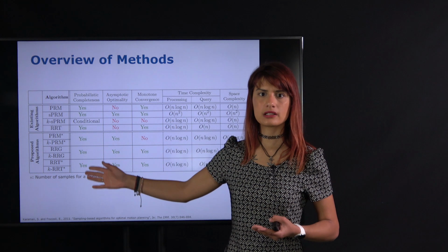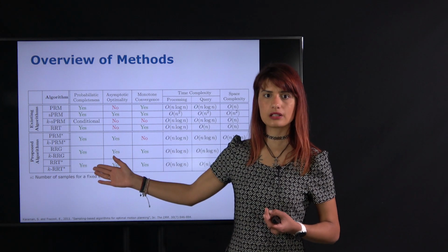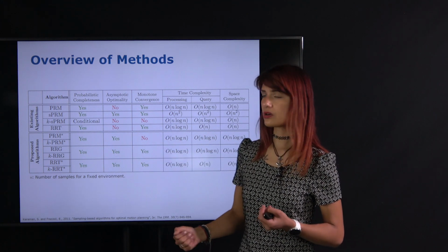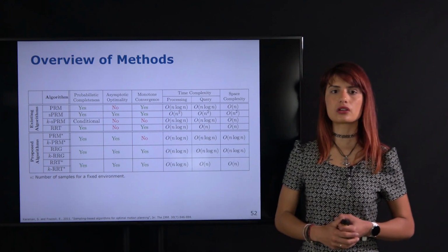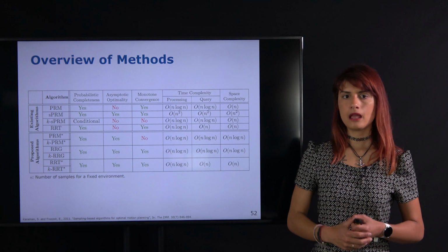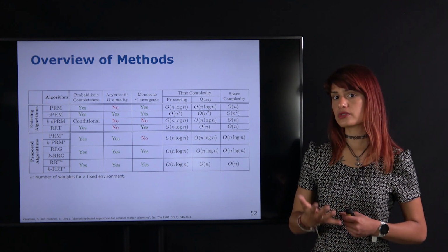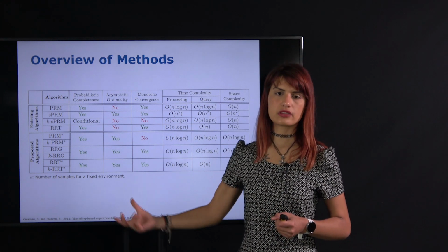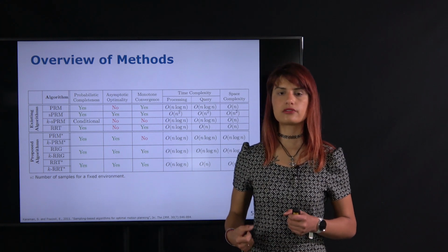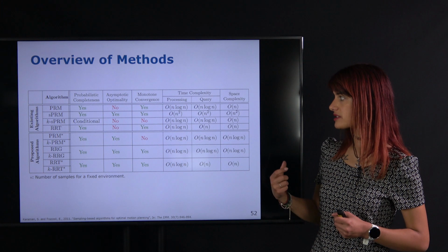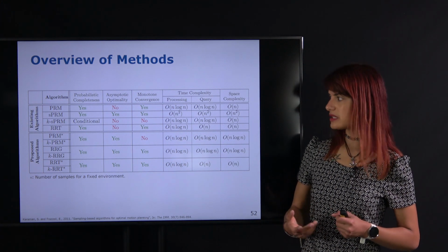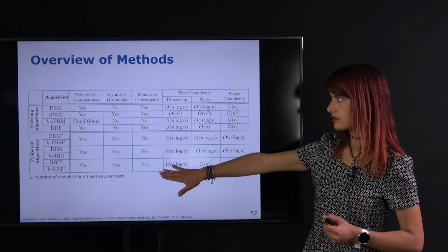Do we want to find a rough solution very quickly using a non-optimal method, for example, the RRT, or is asymptotic optimality very important? And if it is, and computational efficiency is also an issue, then we definitely need to think about some methods of checking collisions more quickly or similar, in order to speed up methods such as the RRT star.